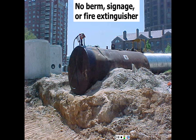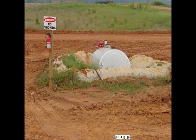Here, for example, we have a large fuel tank with no proper berm, no signage, and no fire extinguisher. So that's a big problem. This one here has a berm surrounding it. It has a fire extinguisher. It has the sign, danger, no smoking. So this is the proper construction of that tank.